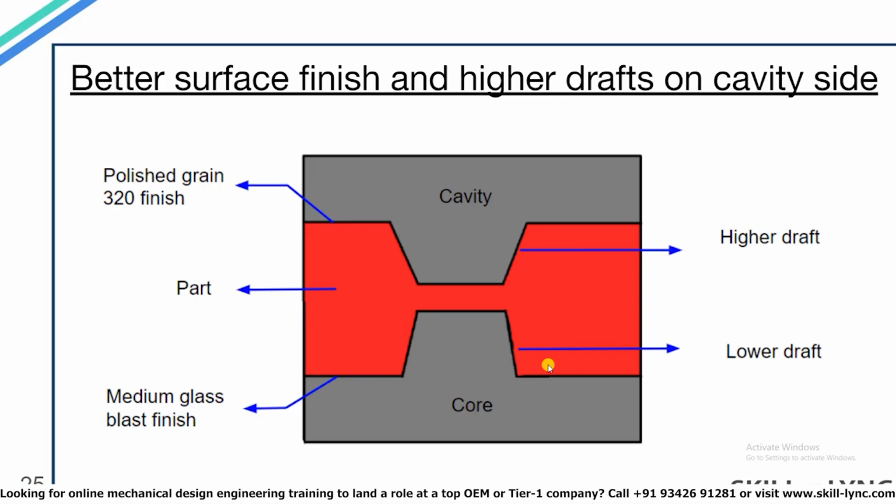If you remember the working of the mold, I had mentioned that the cavity side is fixed and the core side is moving for the 2-plate mold. So when the core moves away from the cavity after the part is formed, the part should come along with the core where it is ejected using the ejection pins. The part should not stick to the cavity walls when the core plate moves back.